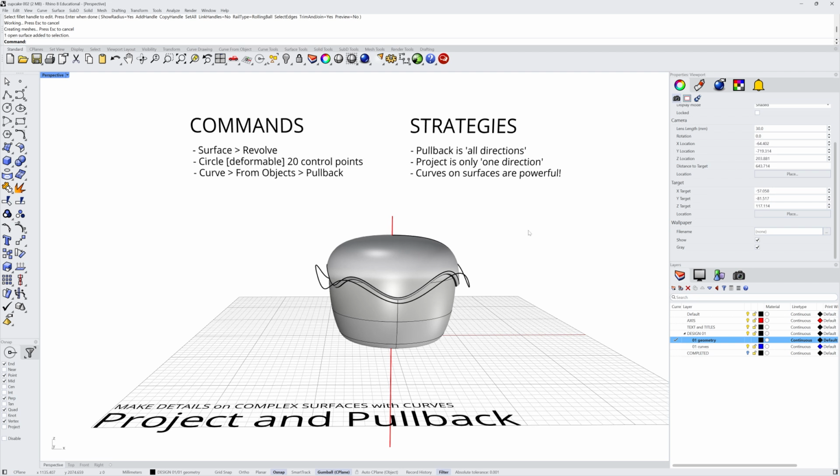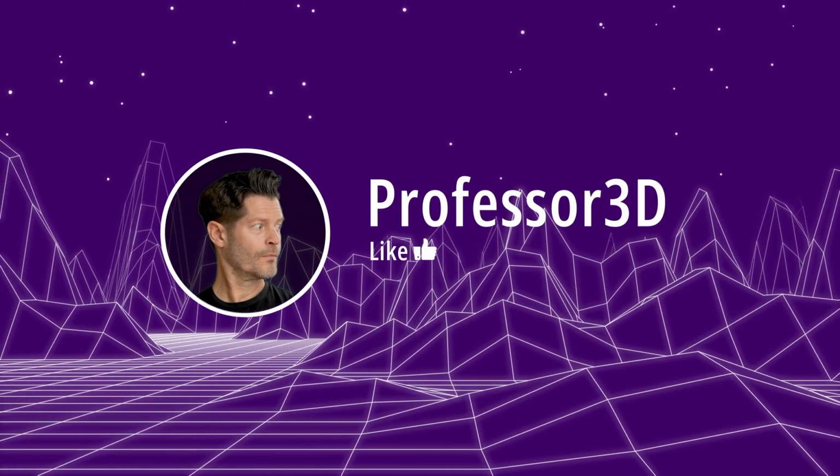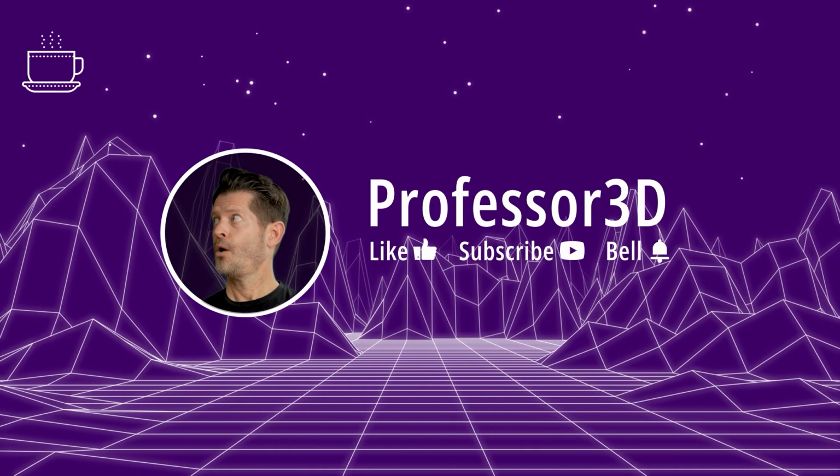So there you go. Just remember, when you do a revolve, always have the two endpoints hit the axis perpendicular. That's important so you don't have any holes, openings, or weird anomalies. And then the goal here is to get the curve onto the surface. You can project in many cases on simple surfaces, but when something is curving in all directions, you want to use that pullback. And finally, use the circle deformable option to kick it up to degree 3, and you can then type in more control points than you normally get.